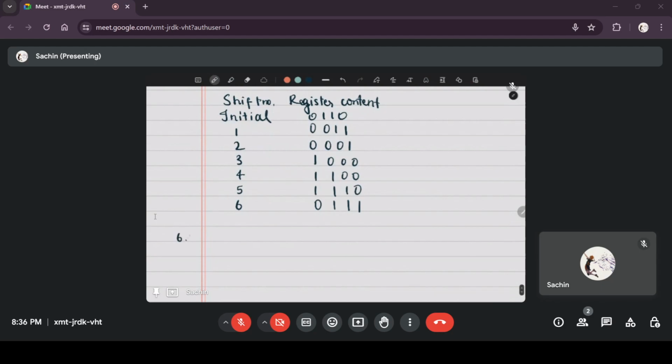Problem 6.5. The 4-bit universal shift register shown in figure 6.7 is enclosed within one IC component package. Draw a block diagram of the IC showing all inputs and outputs. Include 2 pins for the power supply. Draw a block diagram using 2 of these ICs to produce an 8-bit universal shift register. Okay, I'll skip that question.